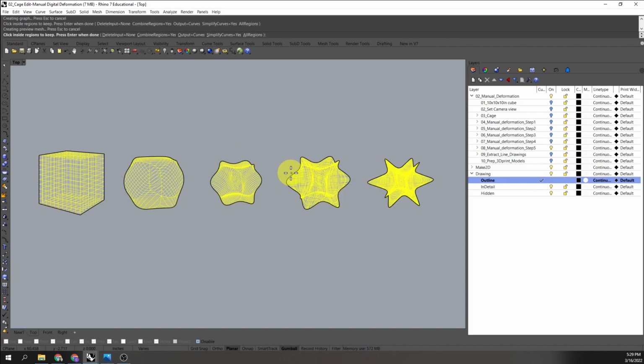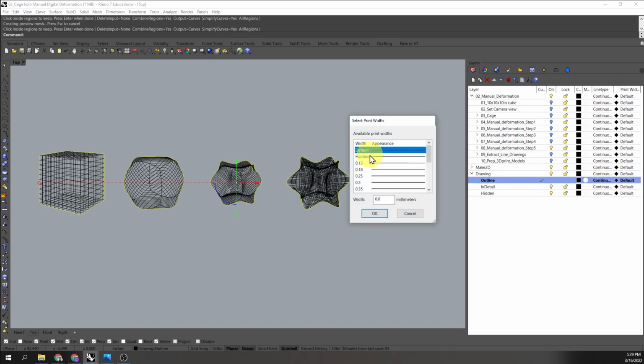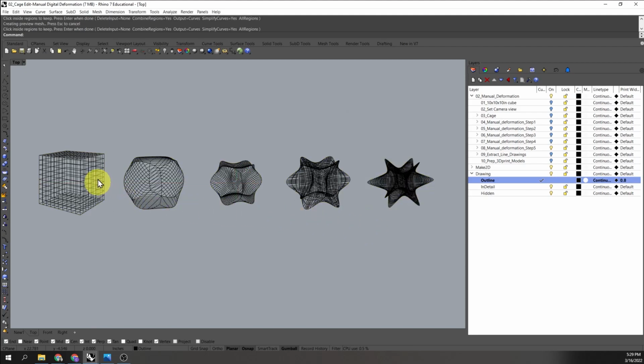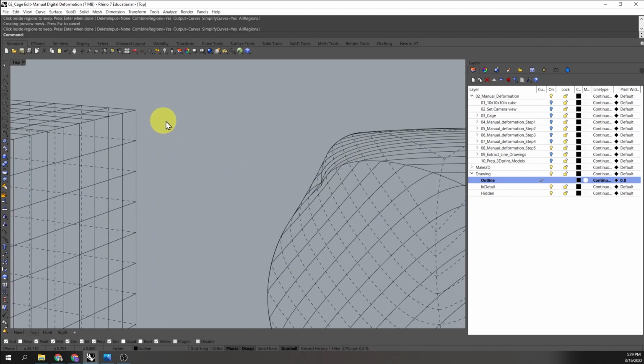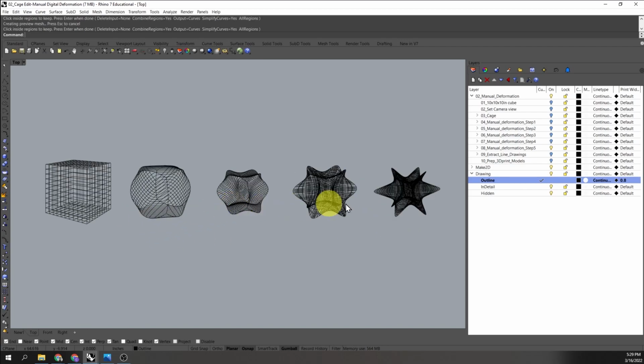I go ahead and hit enter, and now this is under outlines, and right now the line type is set as continuous, which is what I want, and for the line thickness, I'm gonna just give it a nice 0.8 millimeter thickness. The line weight doesn't really change in Rhino. This is something that you do have to go to the preview when you print, or make a PDF and look at it that way.